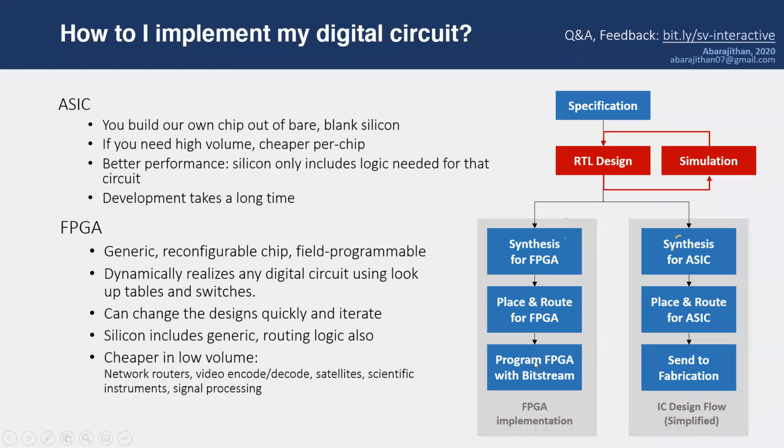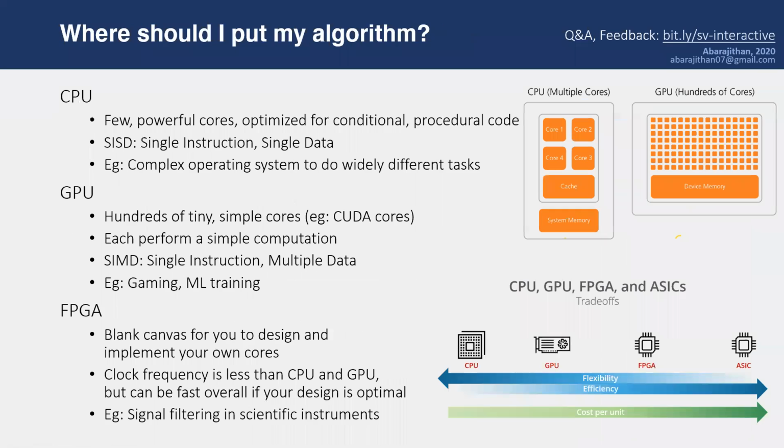And the flow for FPGA is this one. You synthesize; there's a tool, Vivado, you can do that. Vivado does synthesis for FPGA, Vivado can do place and route for FPGA, and you can program the FPGA with a bitstream. All this you can do with Xilinx Vivado.